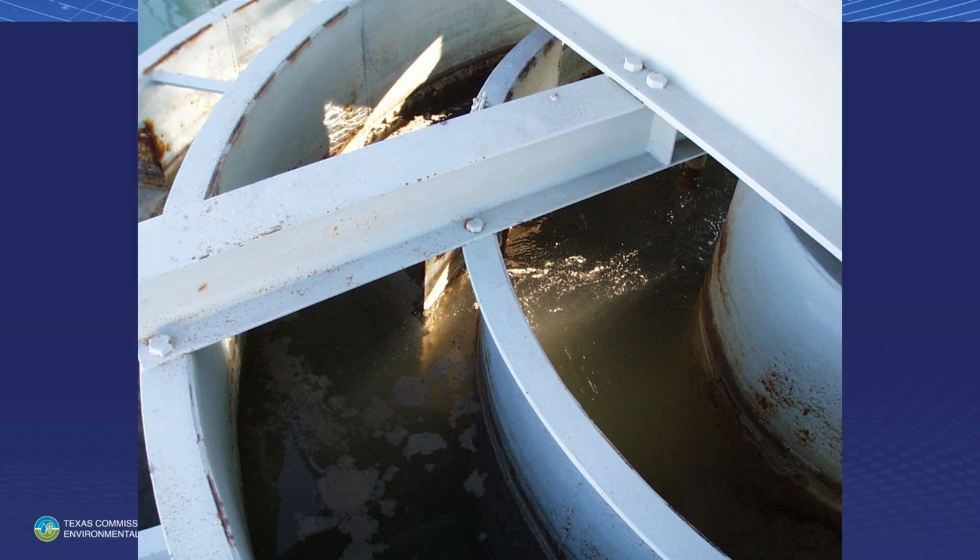This clarifier was really functioning pretty well. Do you see the kind of cloudy marble looking effect that you have right here? In a well-maintained, well-operated sedimentation basin or a flocculation basin, there will be streaks of clarified water that will occur inside your flock blanket coming out of those basins. The old timers called those mare's tails. And it's an indication that your coagulant dosage is set right.